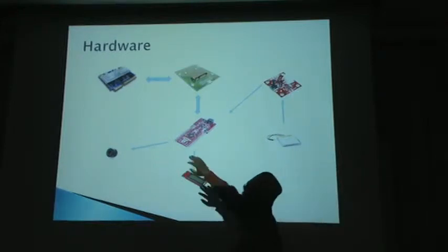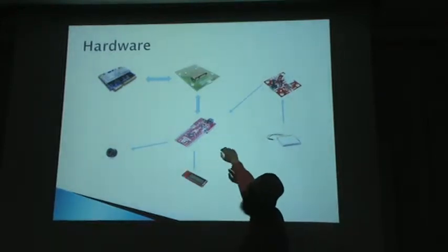So that's our hardware design. We have right here the main RFID IC, the very top one. That's the breakout board for it because, as you can see, it has a PCIe slot, which actually gets into the CPU of the computer. So it's not really that user friendly. We need that interface to make it workable for the pins, so that's why we connected it to the breakout board.